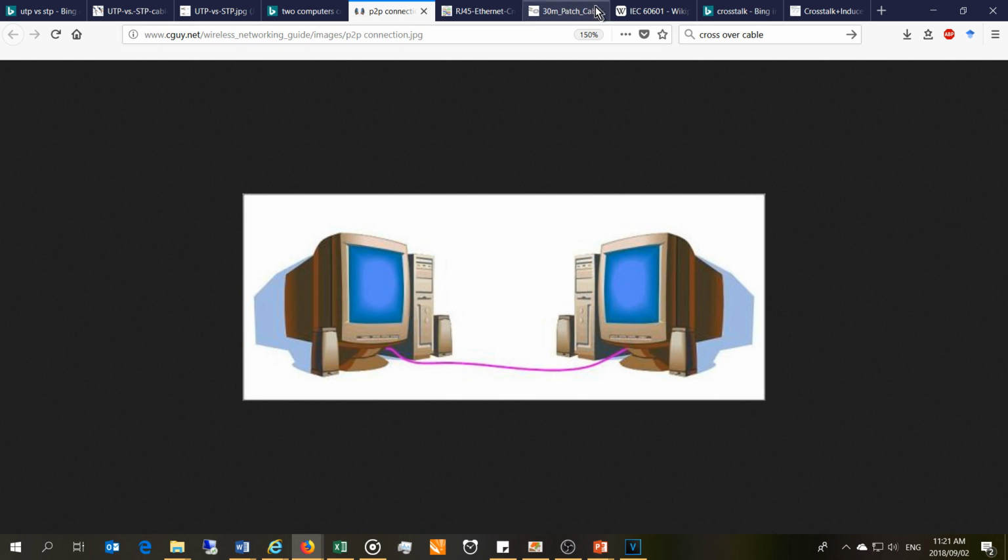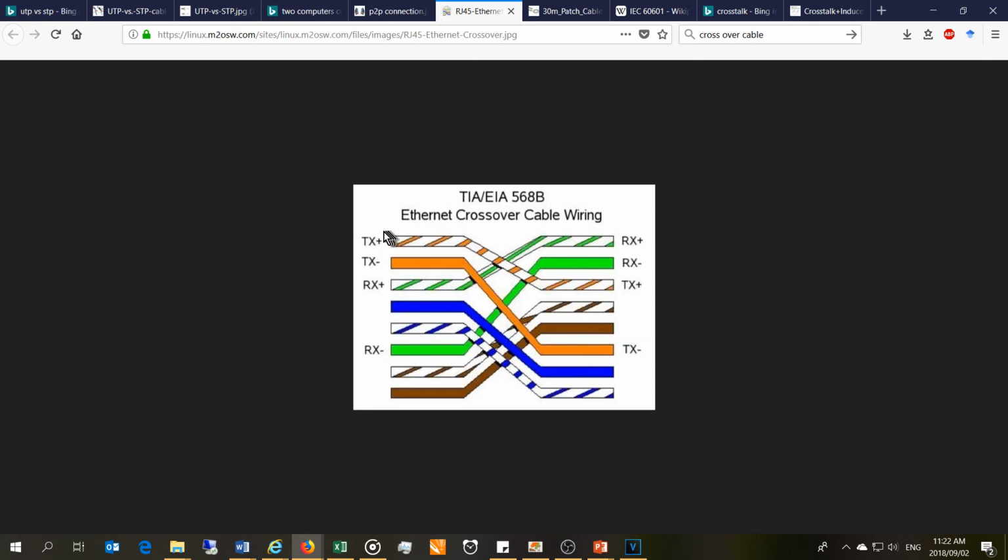And the reason why we do that is it's only 2 hosts. So that means transmitter to receiver, and on this side, his transmitter to her receiver. So what happens is, if we look at that diagram, we'll see that it looks like this. The cable has to be transmitter, has to go to the other person's receive. And this cable here, see when it says receive, has to go to the other person's transmit. So we'll see transmit going to receive, and receive going to transmit.